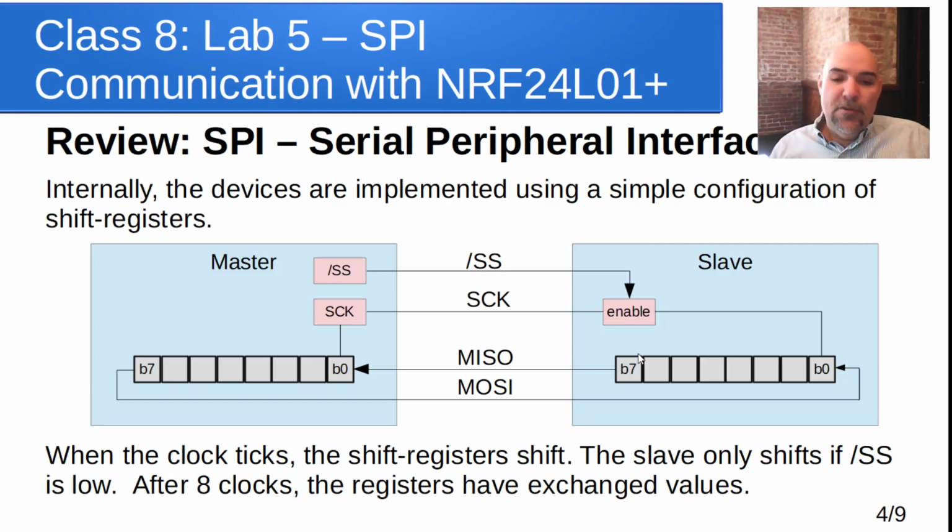Okay, and as a quick review of what happens every time the clock ticks, we want to have the most significant bit go out onto MOSI, and then whatever came in on MISO is going to come in. So we're going to have just 2 I/O lines for this. That'll be laid out in the lab sheet, which I/O line you should use for which bit. But essentially, you're going to mask a bit, the most significant bit from this byte, put it out on the MOSI output, and then shift in.